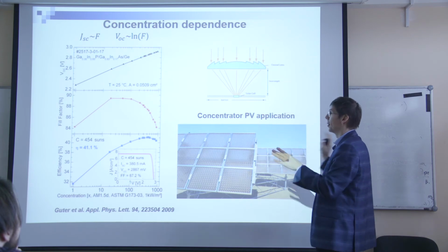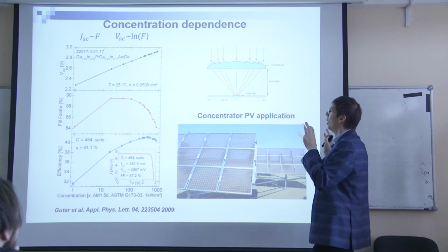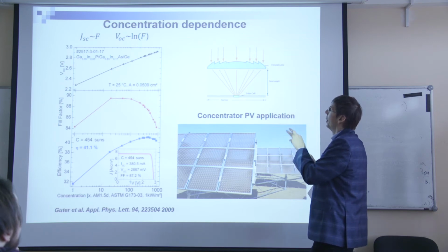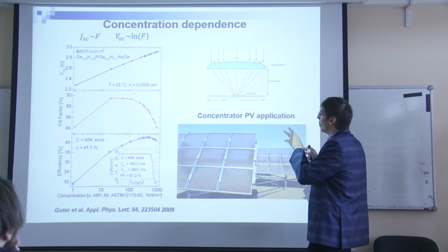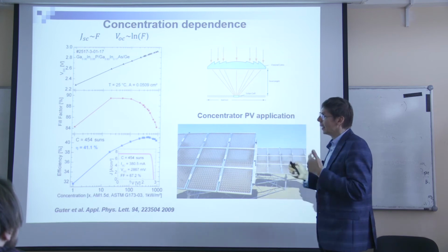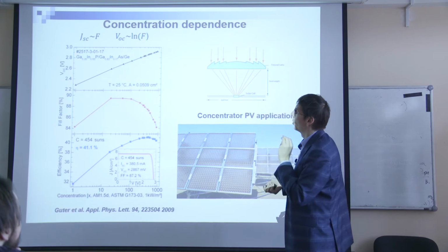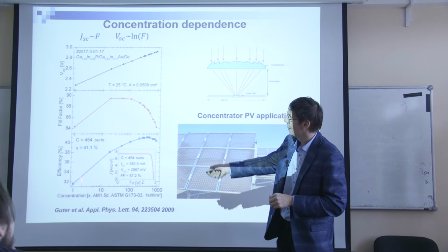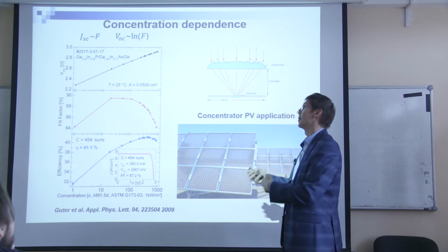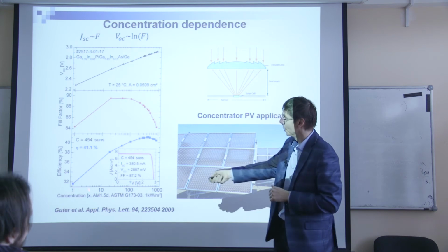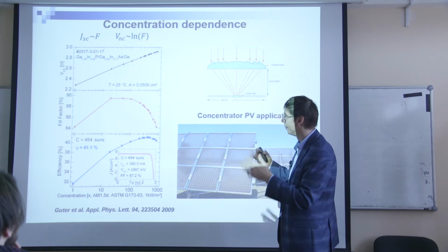There is no reference solar cell for this case, because your measured solar cell is already some kind of the reference. And then you say, okay, for this short circuit current, I know it's one sun, and they calibrate the intensity. So it doesn't mean that they change it, but it's just an example.